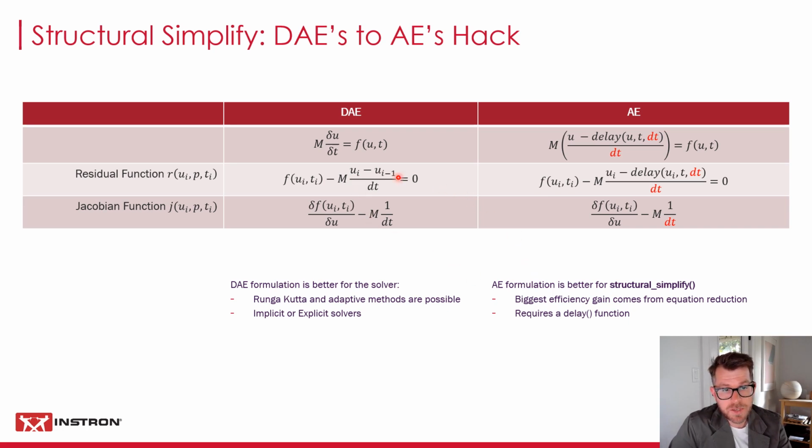If we replace the differential with an algebraic equation using backwards differencing to calculate the derivative, then we convert our model to purely algebraic form, and we're just solving now a set of algebraic equations.